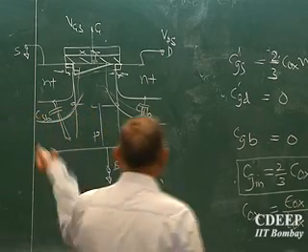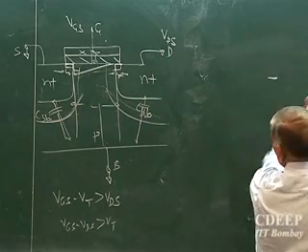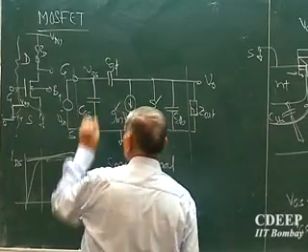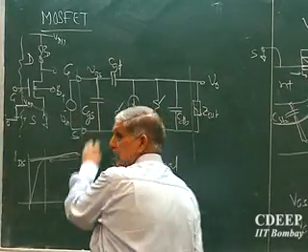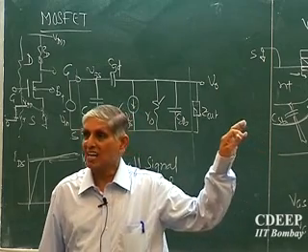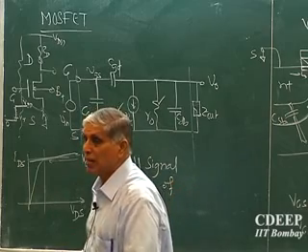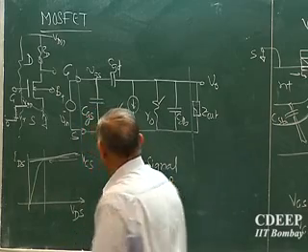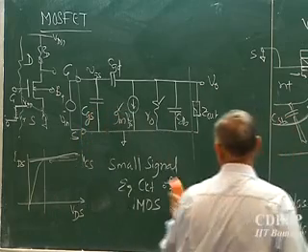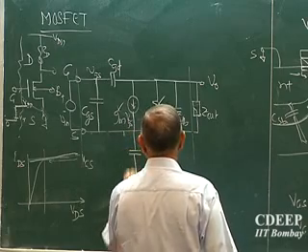So if I use all these capacitances in my circuit, I say, okay, here is the circuit. This CGS actually contains which capacitances? The CGS dash coming from the source side capacitance, whatever you are getting, plus between source and the bulk, there is a capacitance.